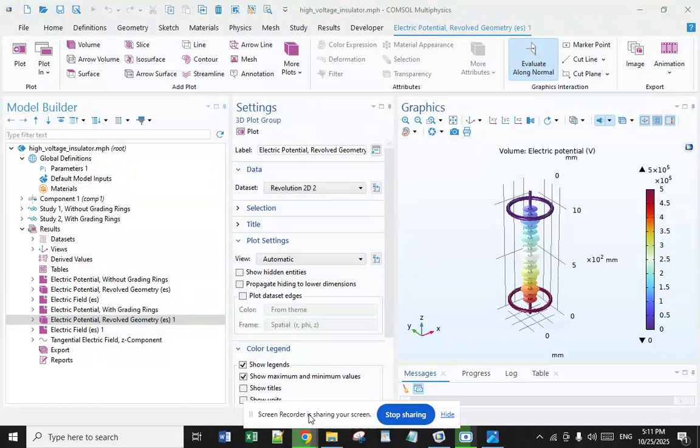The next type is glass insulators. Glass insulators are the oldest and most common insulators in transmission and distribution lines. These insulators are made of tempered glass and are used on voltage lines up to 33 kilovolt. The next type is composite insulators. Composite insulators are made of glass fiber and epoxy resin. These insulators have high mechanical and dielectric strength and are used in voltage lines up to 800 kilovolt.